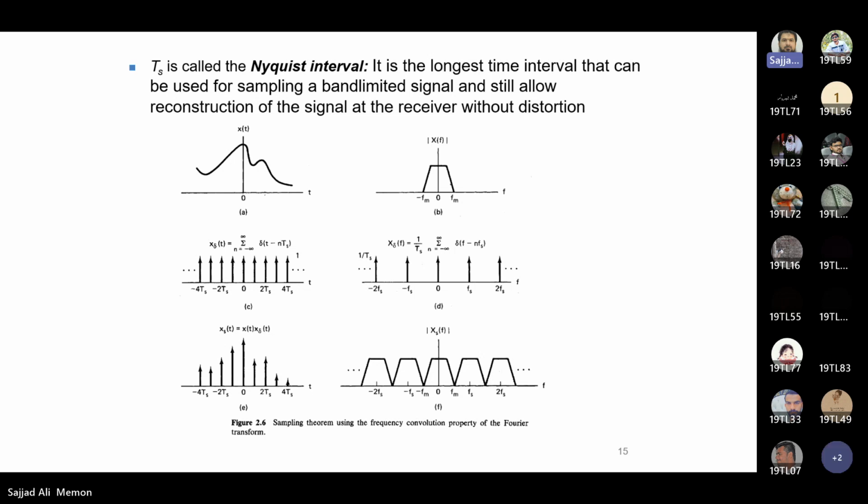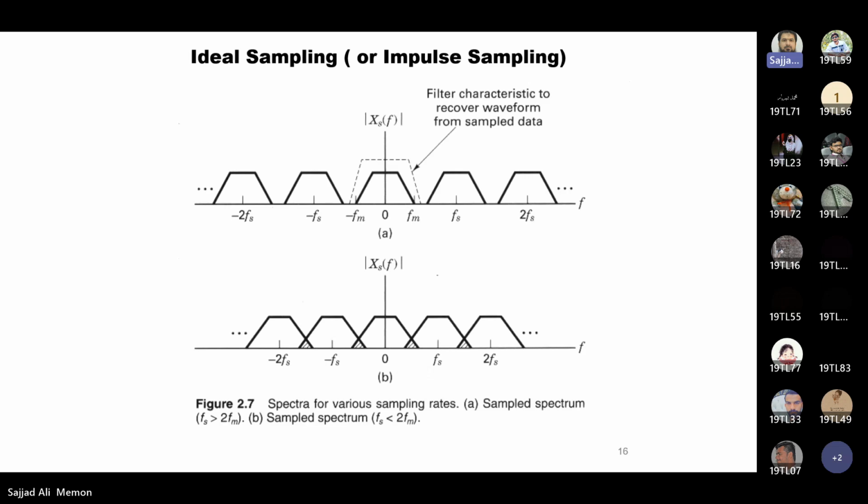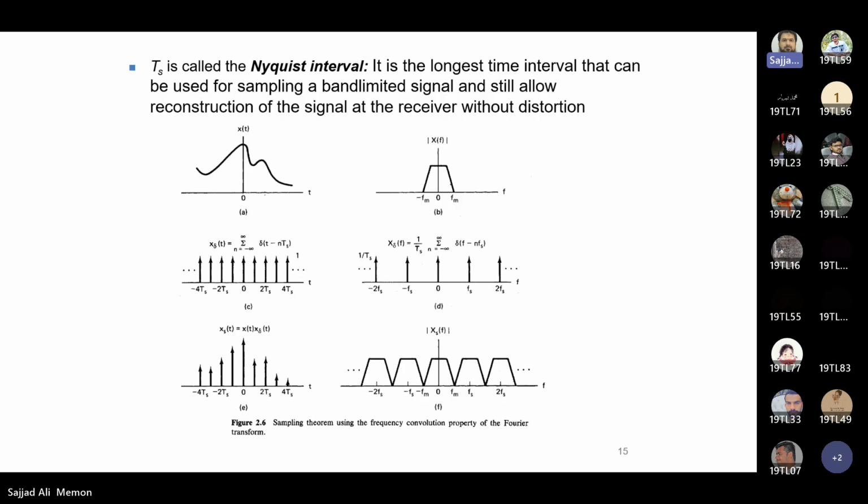This is the Fourier transform or Fourier representation of the analog signal. So we need to recover this one. If this signal is free from other signals, we can filter out this particular signal and convert it using inverse Fourier transform into the time domain signal representation that we have.